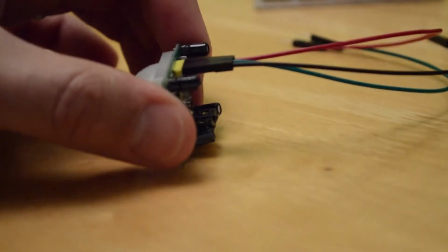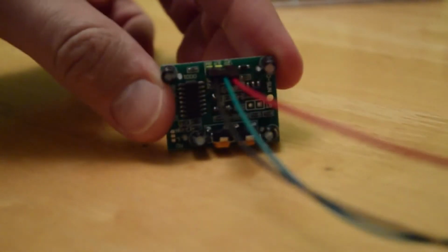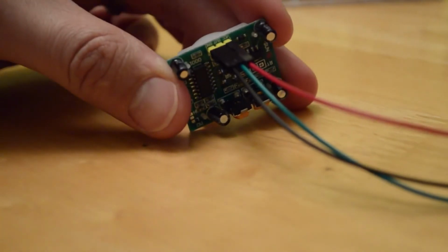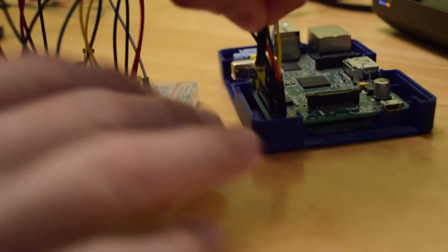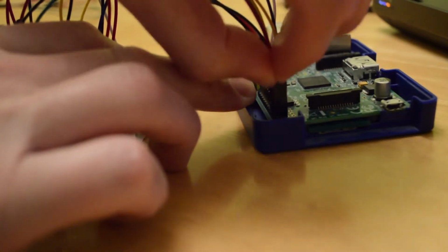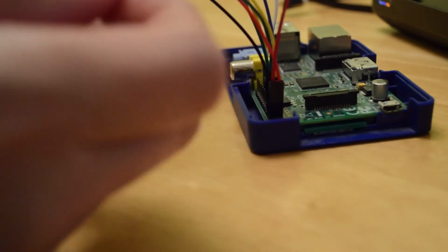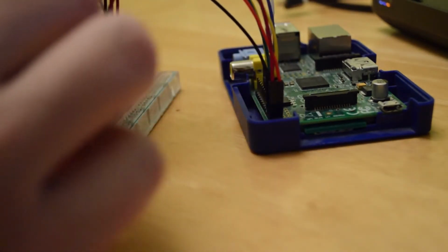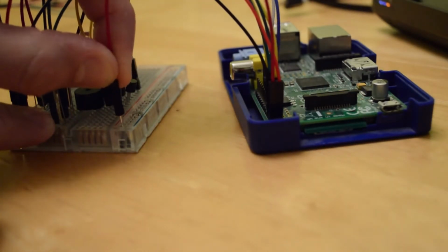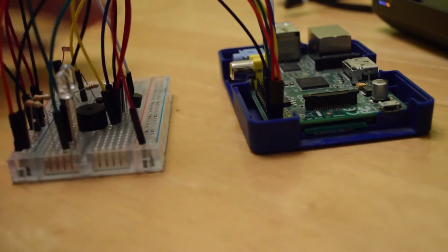So once we've done this, it's great because we've got a bit of cord on this, allowing us a bit of movement, but we now need to connect up the voltage wire. So we're just going to connect this up to the 5-volt rail. Make sure you don't connect this to anything other than the spare top voltage line. You may blow stuff up if you do it to anything other than that. So connect it to that new spare voltage rail there. There's the 5-volt going in.